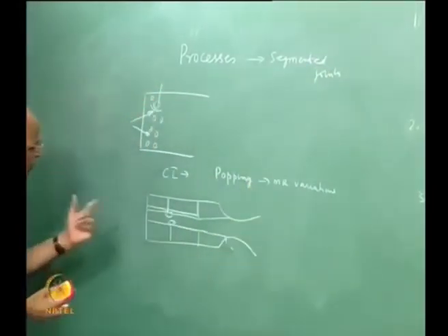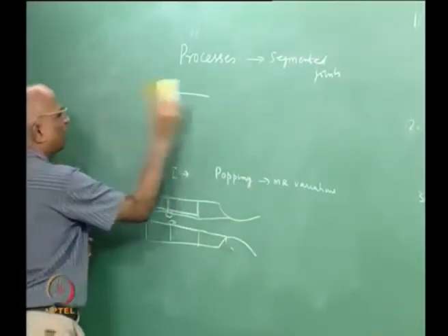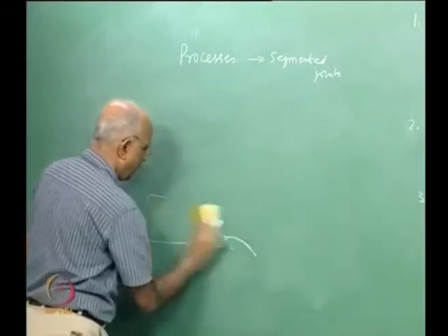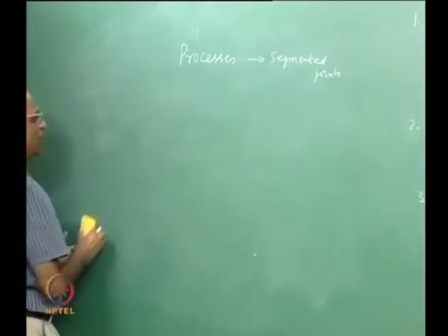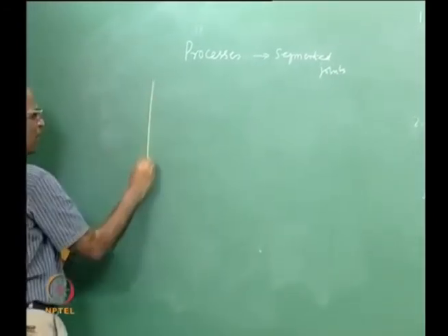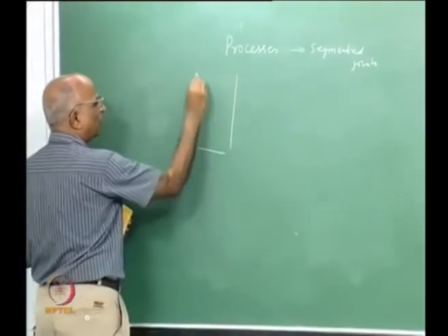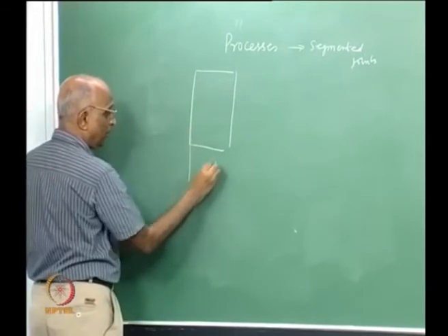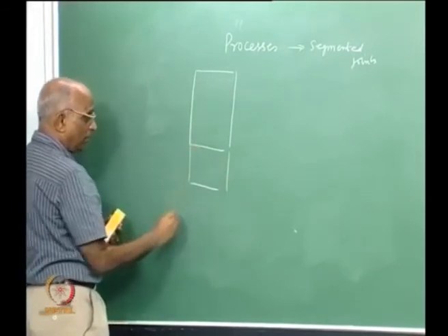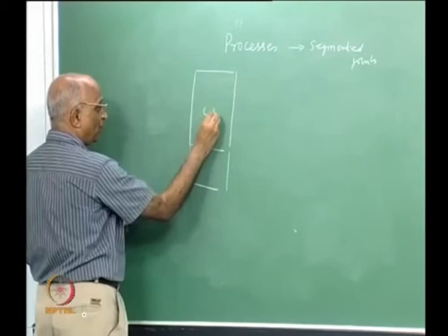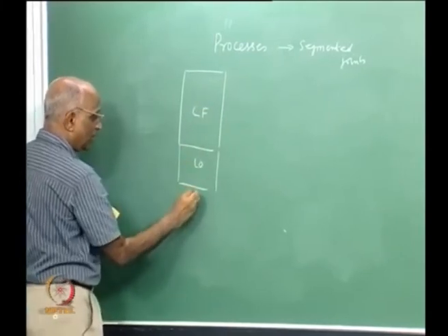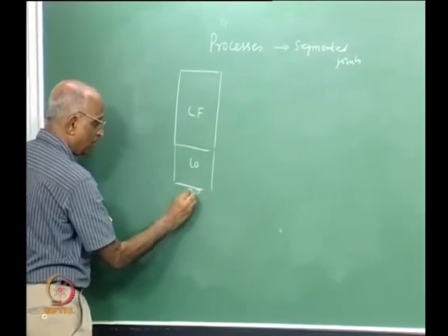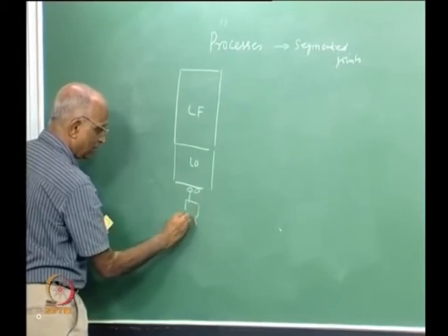I could also think of something else. Let us think of a new process. Whenever I talk about liquid propellant rockets, we have a large propellant tank here, maybe liquid oxidizer, maybe liquid fuel, another tank with a common bulkhead here. Let us say this is liquid fuel, this is liquid oxidizer, supplying through pumps to my liquid engine, that is the thrust chamber.